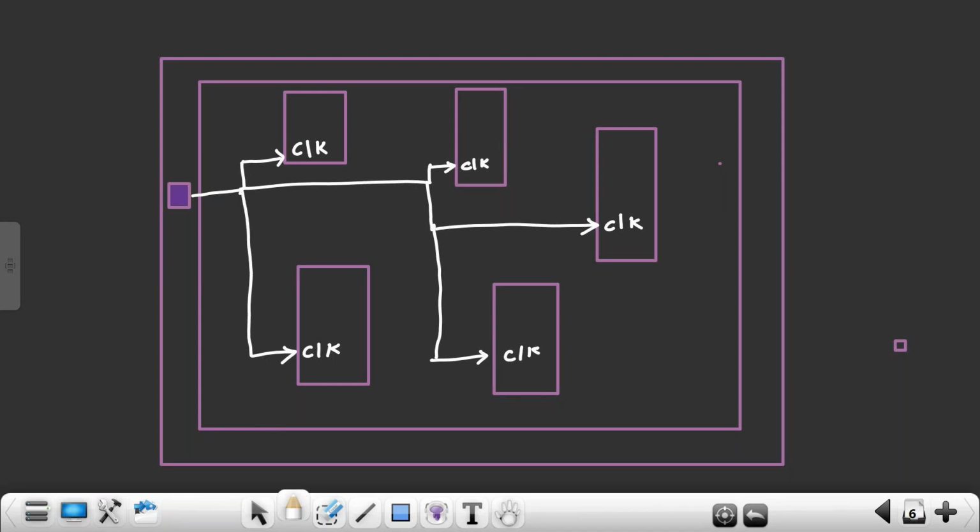It checks the signal reaching all parts of the system. Now it is reaching, right? Now the clock port is connected to all the clocks. It's already connected. So the problem is that the load on the clock port is very high now. This clock port, the load is very high.